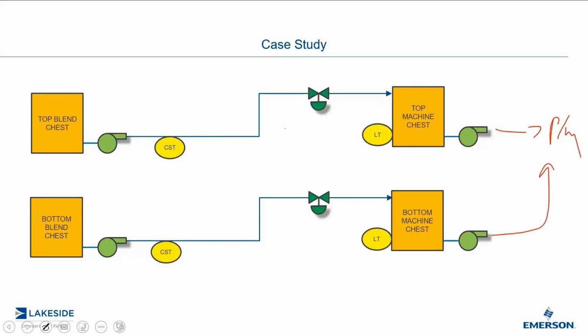It's important when you make paper that you get it right the first time, because if you have variability, if you have oscillations going on here, once you make your paper, that variability is cemented in the paper. It's very, very difficult to undo. You can't put it back into the tank, and sometimes you have to repulp it, which is costly. Here you have a machine chest, which is basically the last tank before you put it on the paper.